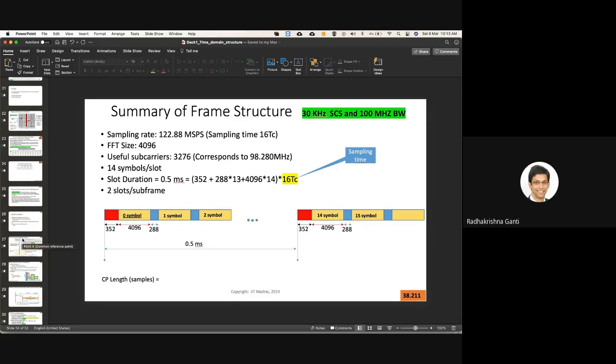We are going to follow the same procedure when we do the course also. Initially, when the UE switches on, it searches for synchronization signals called the SS block, or the PSS and SSS. These are transmitted by the base station. It locks onto the SSS and PSS signals. From there, it estimates the frequency offset, the time offset, and locks onto the resource grid.